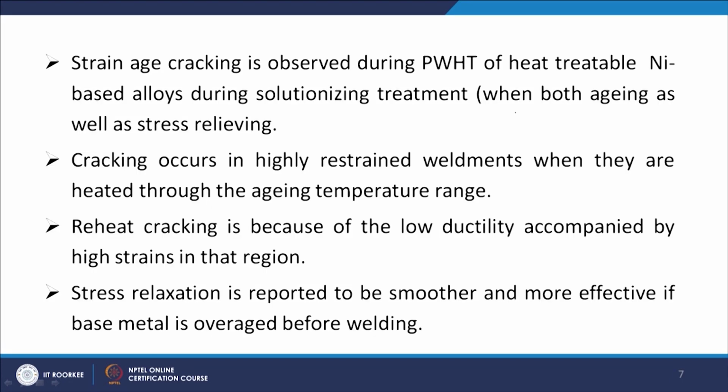Now, many a times you observe these reheat cracks in a different manner. We term it strain age cracking in the case of post weld heat treatment of heat treatable nickel based alloys. What we do normally is solutionize first, and then two things happen: one is aging and another is stress relieving.